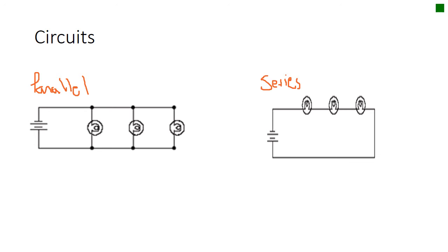Parallel circuit has more than one path. Okay. So current passes through each and every single load. So the advantage of this parallel circuit is, if we break the current here, then it's not going to affect the functionality of the other bulbs. They'll still work. Adding a new pathway with an extra resistor will not affect the resistance in any of the other pathways, but adding more resistors in parallel will decrease the total resistance of the circuit.